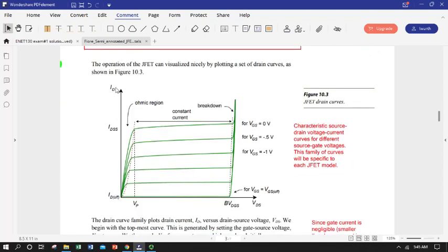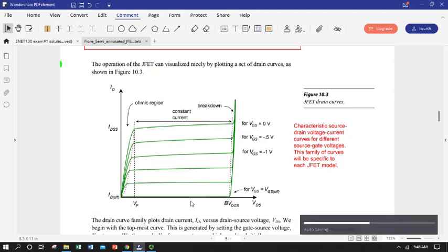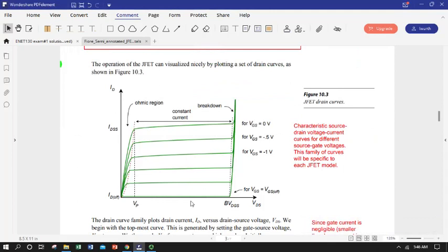So here's our plot. Here's our measured quantity, our drain current, and on our x-axis here's our source to drain voltage. Again, this is the same idea we've brought up before, where we're looking at the current-voltage characteristics of a device. If I put so much voltage across a device, how much current flows under what other conditions? In this case, our other condition is our gate to source applied, quote-unquote, throttling voltage.